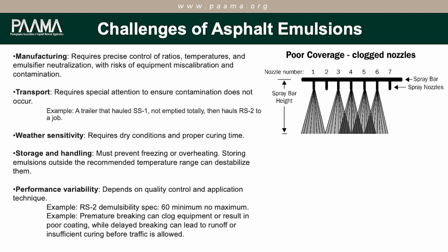Next, we have some of the challenges of asphalt emulsions. On the manufacturing side, this requires precise control of the ratios, temperatures, and emulsifier neutralization. One of the big risks is not totally being calibrated, and contamination. So if our pumps and meters aren't exactly where they need to be, you don't know exactly what's going into your final product, and it's not going to test out correctly. So we have to be on top of that constantly.